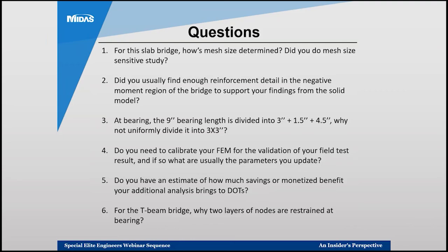So if you're doing a plate element, you want to do it 6x6, but you can go sometimes to 2. I would say 3, 4 is kind of the agreed on limit, but I personally like to avoid the aspect ratio of 3. Size-wise, I think for this slab span, we were looking into 6-inch element size, if I remember correctly, but that typically will go between 4 and 12 inches. It again depends on the size of the structure, how many spans you are modeling, and how fast your computer is. And sometimes, even if you refine more, you are not getting anything more than that.